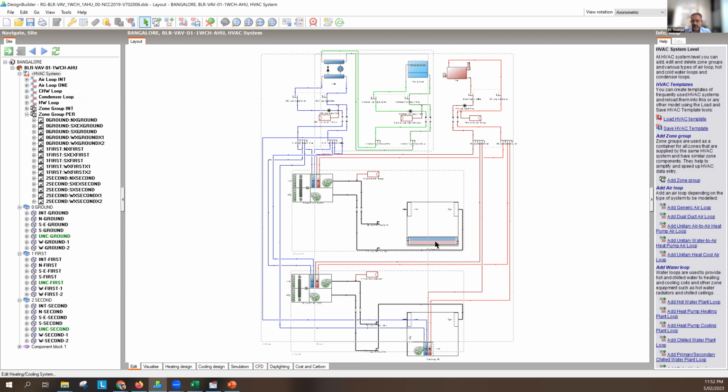In that case, you will get condensation on those panels. And as I said, in extreme cases, it may rain. But I know there's a lot of radiant systems in Hyderabad, Bangalore, Ahmedabad. These places are dry. They will work really well.